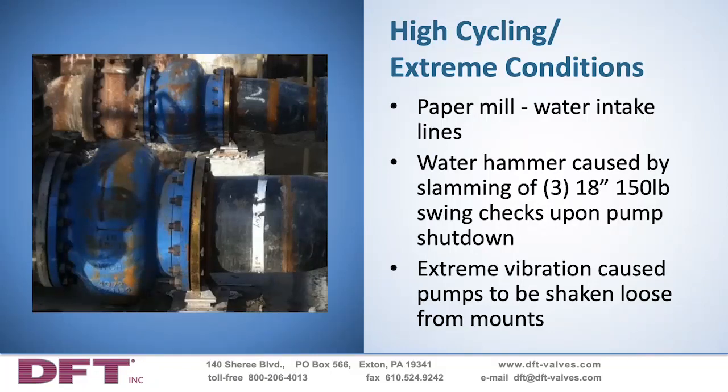So not only were they having problems with the damage to the swing check and the internals of those swing check valves, but they were also causing the pumps to become loosened from their mounting support systems. The solution here was to install 18-inch model GLC check valves from DFT. These were carbon steel bodies with stainless steel internals. A spool piece was added so that the overall length of the GLC would match the B16.10 face-to-face dimension of the swing checks that were there.